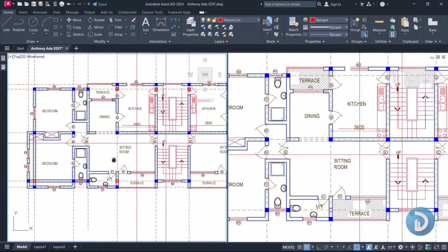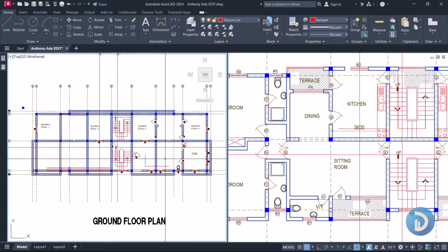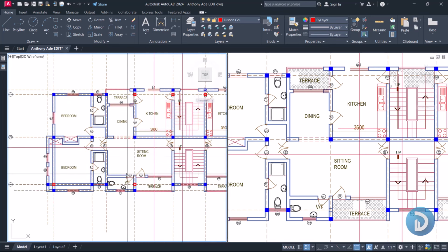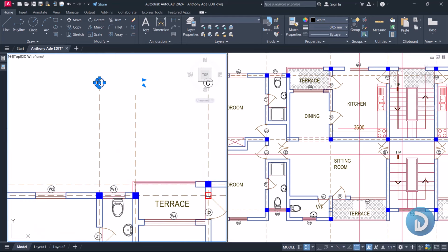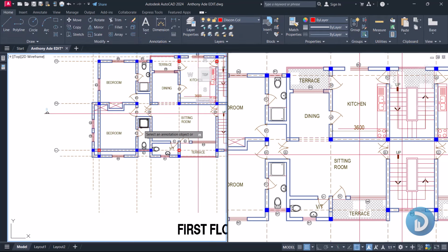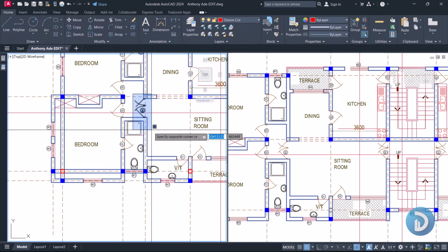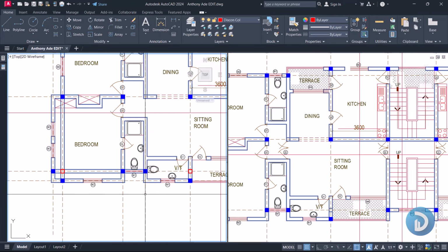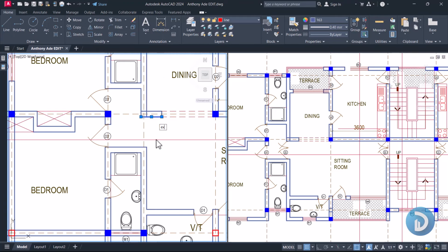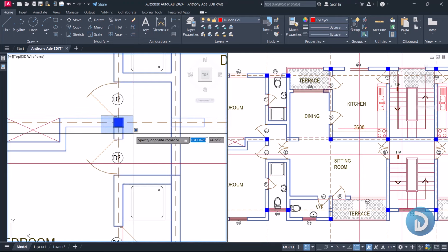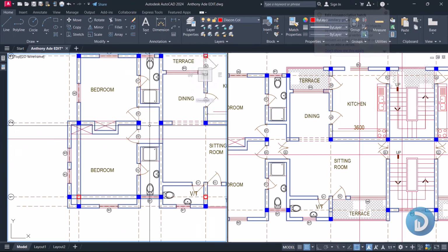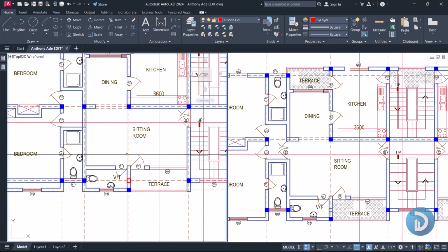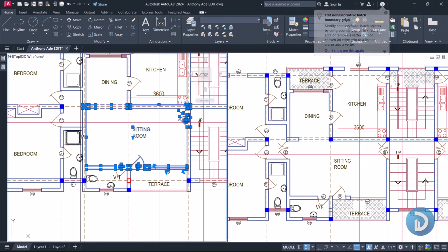So what we'll do in this case is, against having that beam running on grid line C, we'll come here to this part and we'll run our beam on grid line B asterisk. So we'll copy this from here to here. We'll edit this to be asterisk. So we can choose to delete this part, and this beam will be constructed on the block wall, so it will be hidden. So we can choose to extend this here and come here to, let's say we introduce a new column here. So we can treat this as one panel, and we'll treat this other part as another panel.